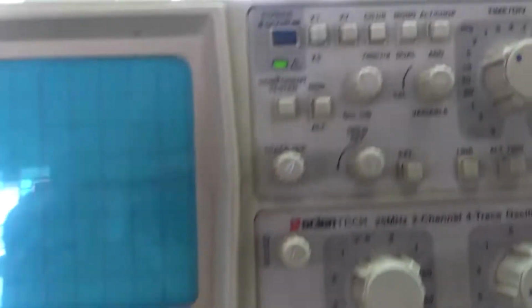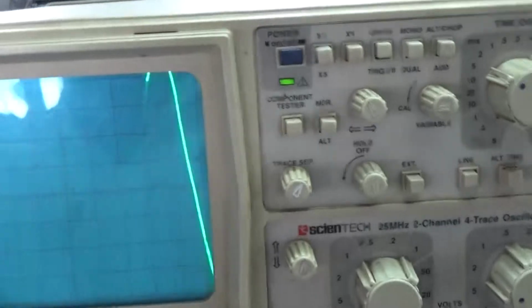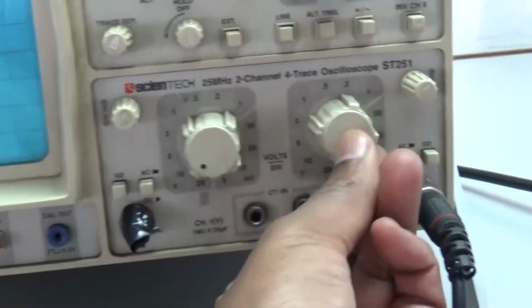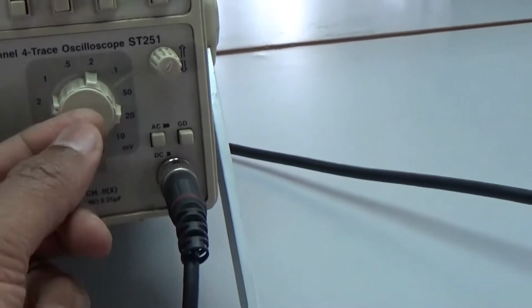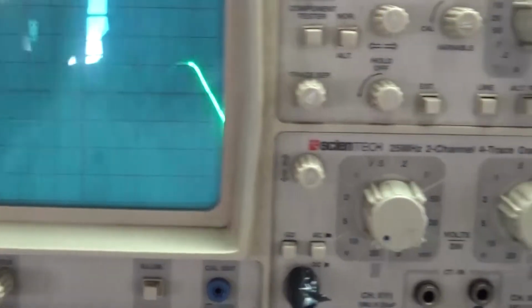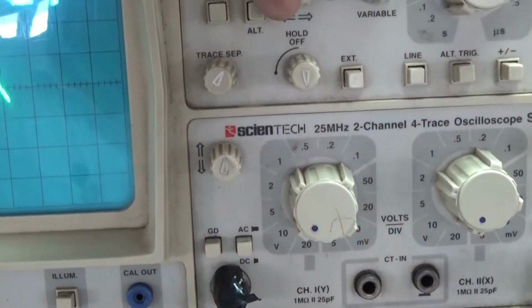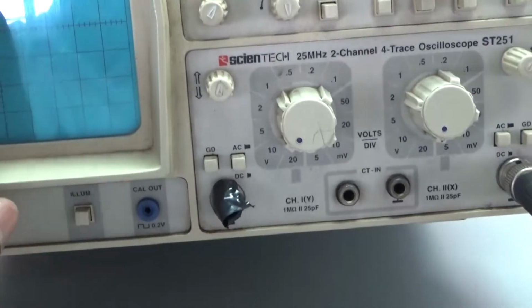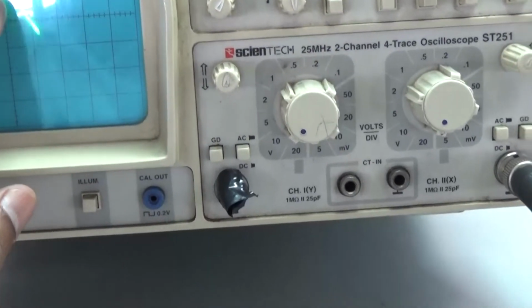If you look at the CRO here, since the voltage is exceeding the values, set the voltage knob here. This is our y-axis, this is the time knob, and let us see what's the amplitude we are getting here. So when you look at the amplitude, we are getting around 1.1 unit peak value or the amplitude.